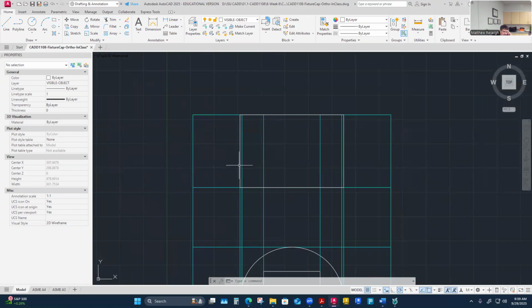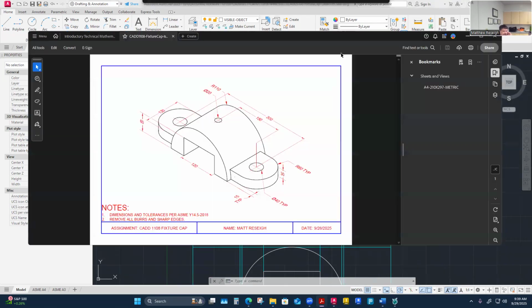Looking at this, I'll say that it is a radius of 60. And it's on center here of the part. So this is a symmetrical part. If I was to slice it down through here from left side to right side, it would be symmetrical front to back. And it just helps me place this ear in the right spot. I just need to come 60 over, and the hole in the ear and the radius of the ear are going to be concentric in this case. You find that relationship a lot in part manufacturing.